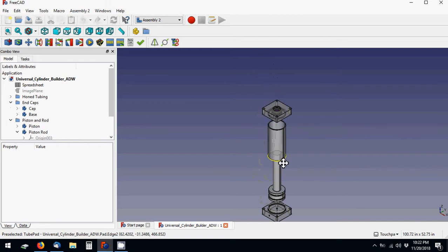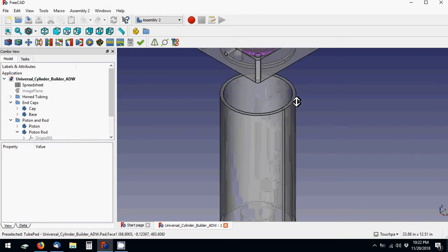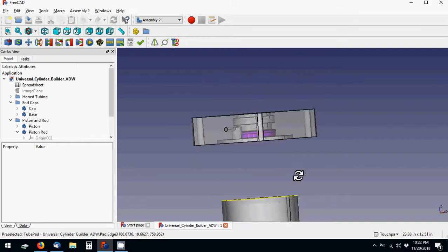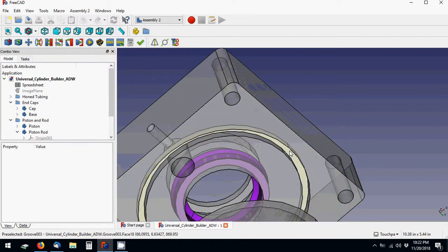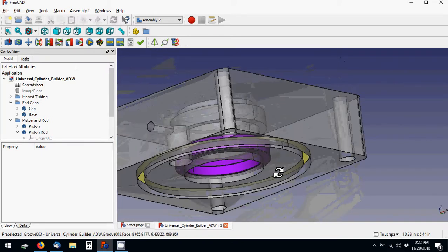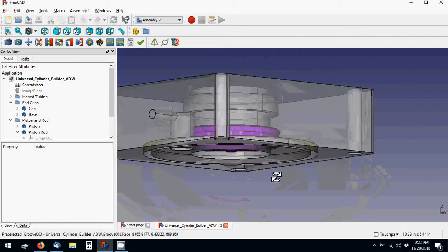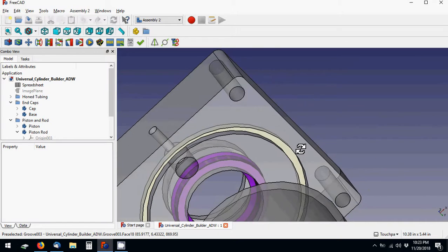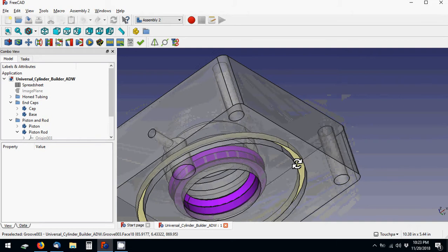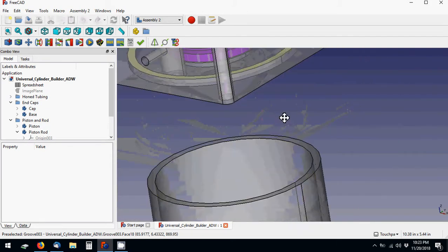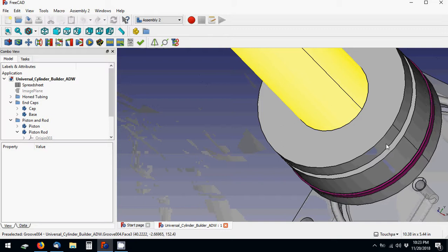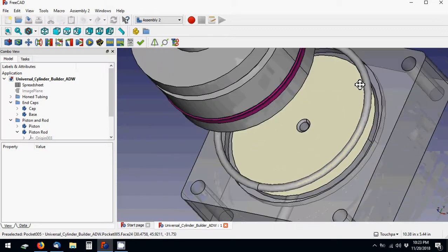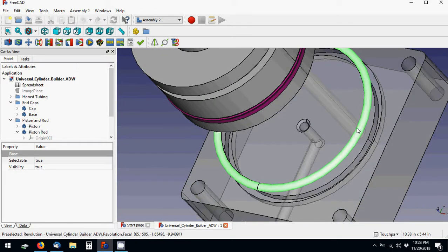Just real quick, the way that the tube seals and the caps is in this trepan groove, and I've actually only ever seen that in writing, so I may be pronouncing that wrong. But this trepan groove, I think it's default to the same as the wall thickness of the cylinder, and obviously that's a little bit shallow. So actually, when you use an O-ring with that same diameter, that's going to be too thick.